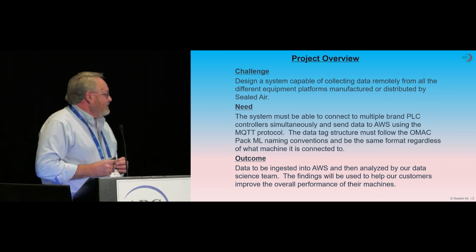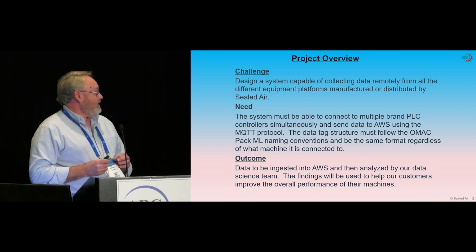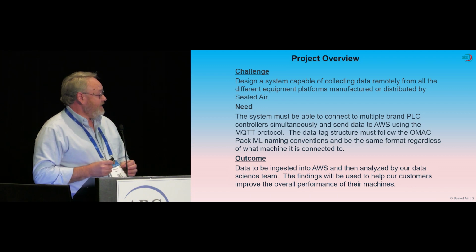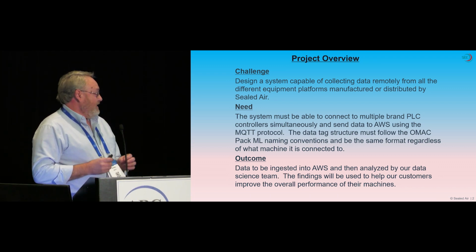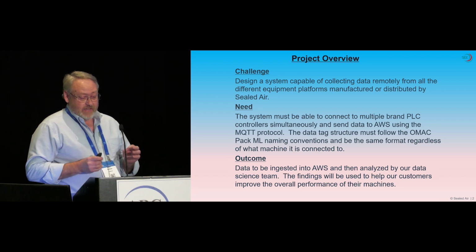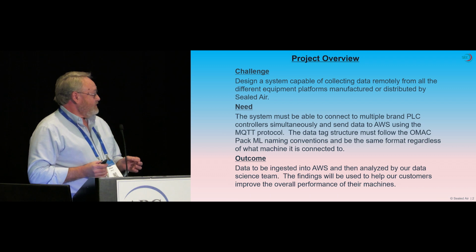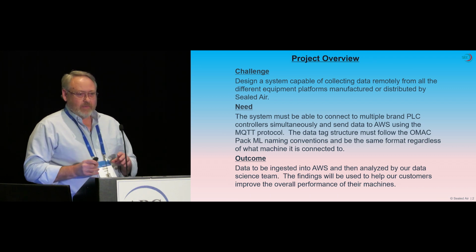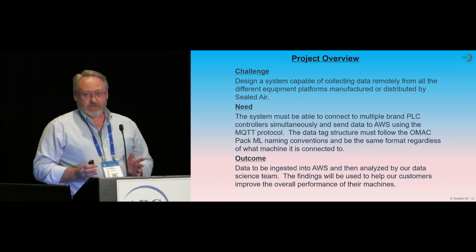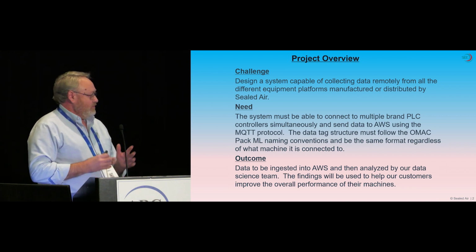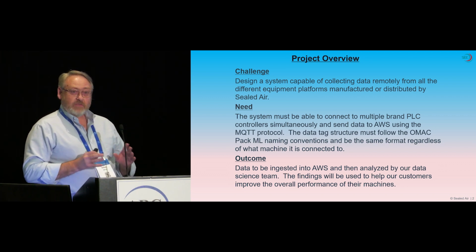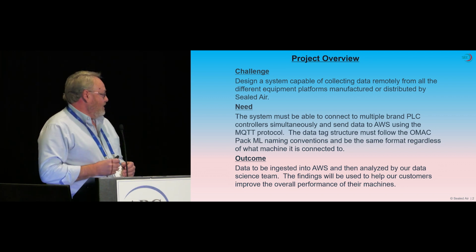Our needs: we must be able to connect to multiple brand PLC controllers simultaneously and send data to AWS using MQTT. We wanted to follow a standard data structure using OMAC PackML for naming conventions. And we wanted to have the same format regardless of what piece of equipment we're talking to, regardless of the manufacturer or controller. Everything we wanted to be the same.